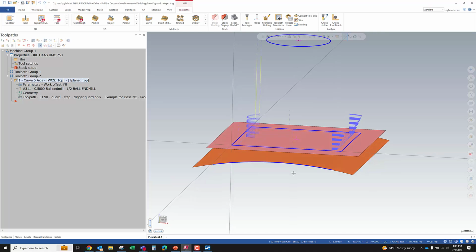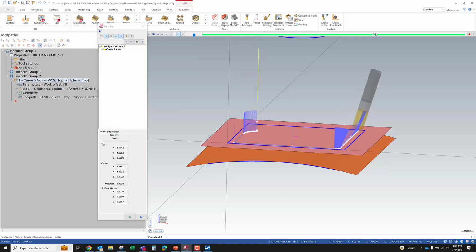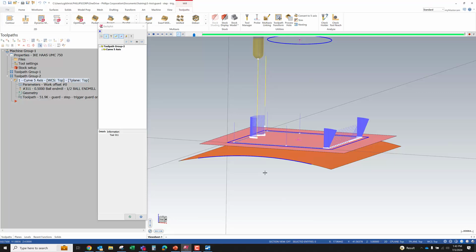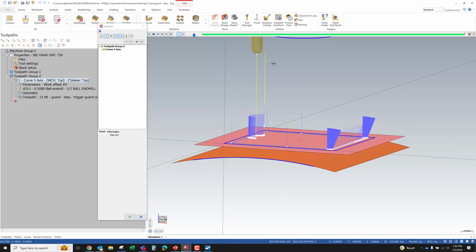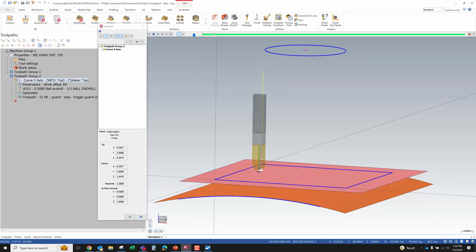What's a good result? What's a good result for a 5-axis toolpath like this? Why do I think this is a good result, whereas what we had previously was a bad result? This is a clean toolpath to me. This is the standard by which I judge every other programmer in the world. When we're creating a path within reason, does it have kind of one high start point, which is the safety block that you're going to see in your NC code, a nice, safe, clean, smooth approach?